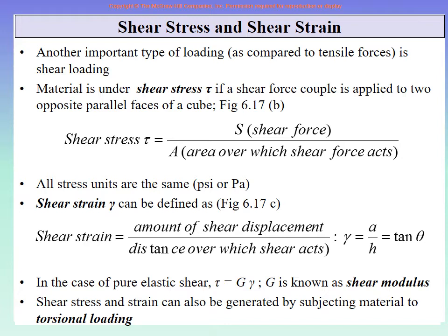If you remember, I don't know if we discussed it, that when we are applying normal load and we are talking of a stress and a strain, then if the deformation is elastic, when you remove the load, all the deformation goes away. So how is elastic deformation defined technically? For all metals and alloys, it is a straight line, right? A straight line means that both the quantities, stress on one side, strain on the other, it is a straight line. So both the quantities are directly proportional.